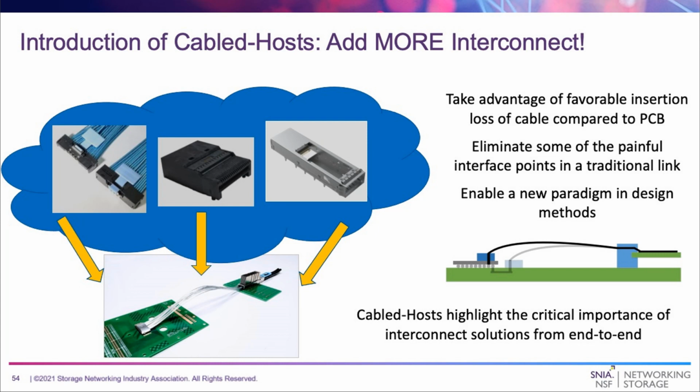And so the thought is that you would combine some of the dense, low profile connectivity of the inside-the-box solutions with panel mounted versions of the pluggable I/O connectors that would connect to the same passive or active copper cables or optical modules that we talked about earlier in the discussion today. And so that connection point could be next to the chip or possibly integrated into the chip package to create an optimized path that would be needed to support these next generation data rates. I've shown that in the picture on the right there.